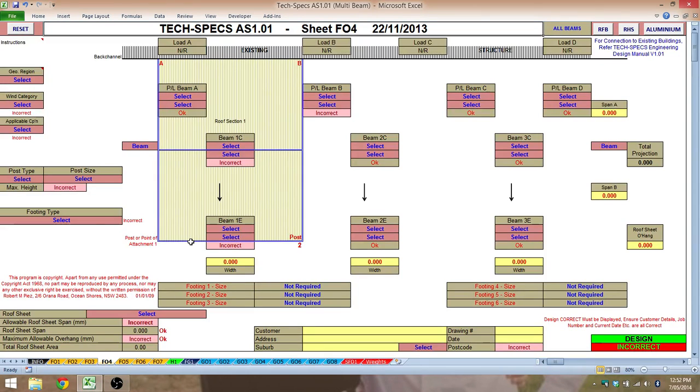Flat option 4 is for designing point load beam patios. So where you might have the requirement for a central beam, but the customer doesn't want any posts out in the middle at all, you need to run a beam out either end to support the central beam in the middle and just have posts out the front.